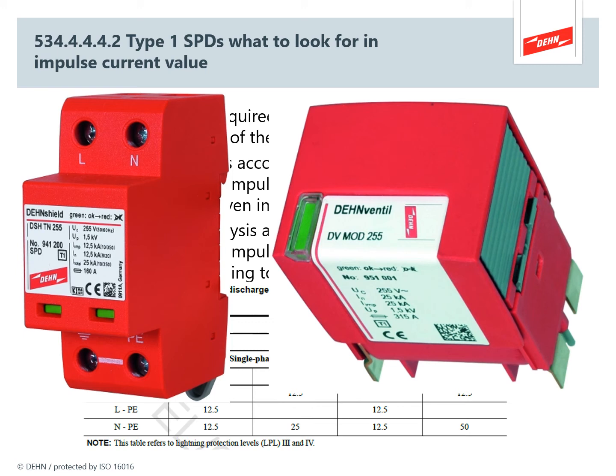And this isn't mentioned in 7671 or 10101 because this is normally the remit of the lightning protection contractor once they've established the lightning protection level as being level 1 or 2 through the 62305 risk assessment. On the label here we've got 25 kA per pole, a low let-through value of 1.5 kV, and fusing is rated at 315 amps. So that's something to bear in mind when we go on to the next section about fuse ratings.